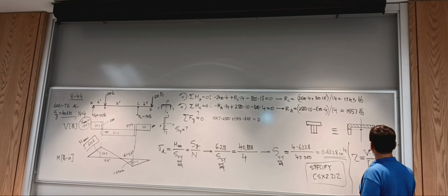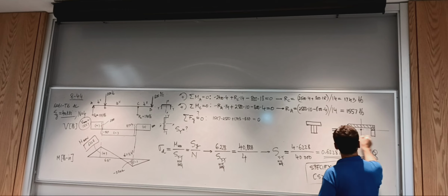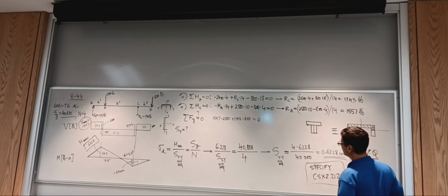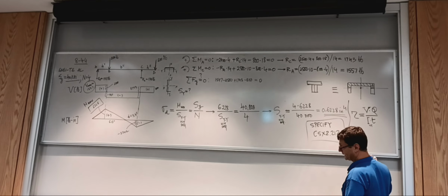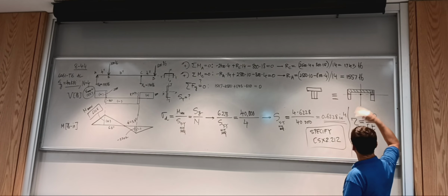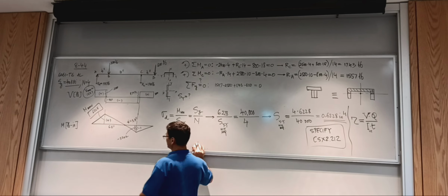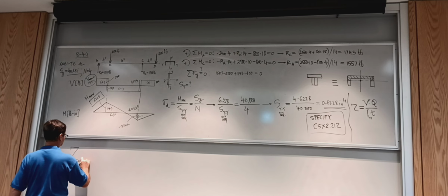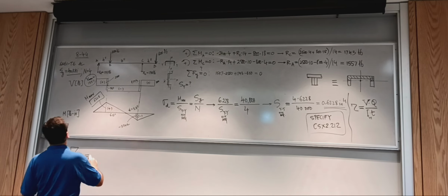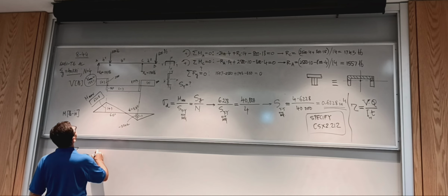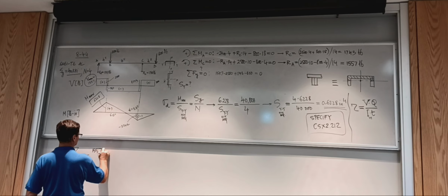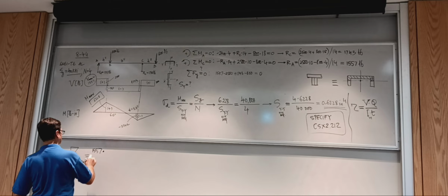This will come out from the table. T is going to be twice the thickness of the flanges. This is the web. And now Q, we can take either the above or below. That might be a good opportunity to verify what I kept on saying, that you either take the above or the below Q. So let's look at that tau there. Let's put in some values, tau max. So V to begin with, what was it, the maximum? 1,557. And then I have Q to calculate.